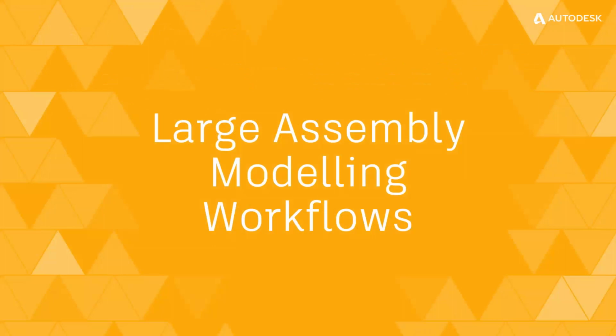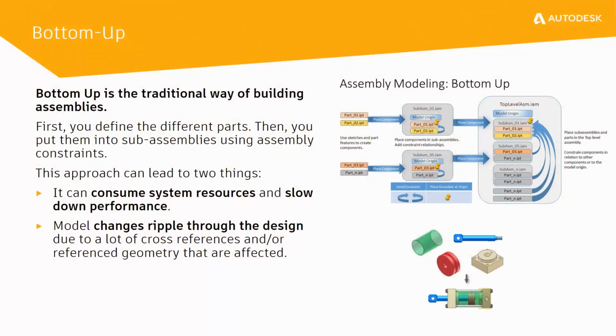So finally, let's move into large assembly modeling workflows, and there's a number of ways that we can work with our data when we're working with large assemblies. One of the more common ways is bottom-up, a more traditional way of building assemblies, the way that I was taught many years ago to design, almost the default construction methodology. So it's no surprise that many of you may already be using this. The challenge associated with this is that it consumes a lot of system resources and can significantly slow down your overall system performance.